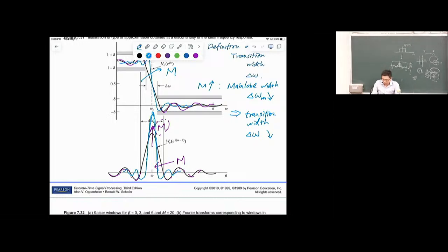And that's desired. So again, before you go home, remember, increasing M leads to a better performance in terms of transition width. So again, you see an example of trading computation load for better performance. If you need a faster transition, we need to be willing to consume more power or enlarge your VLSI circuit area. This is inevitable. Better performance, you need to sacrifice. You use more budget, more money. All right. Any question right here?